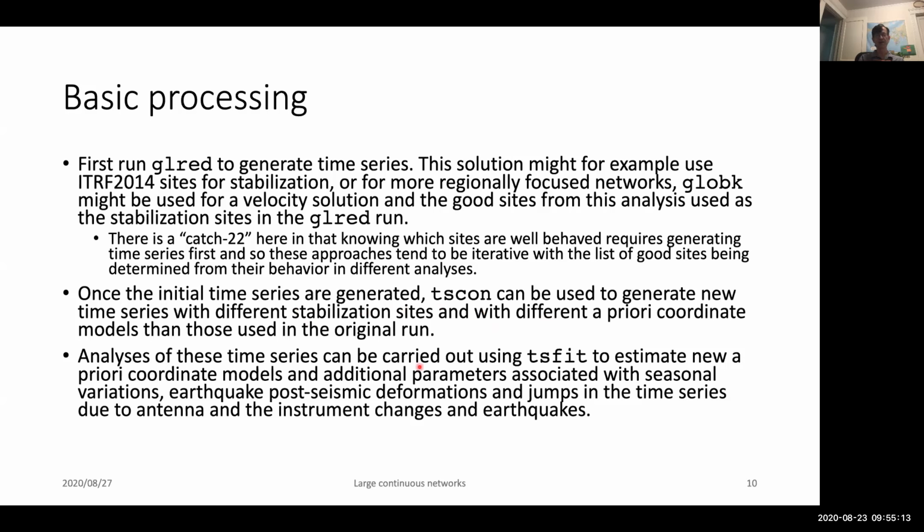You carry out the analyses of these time series with tsfit, and then there's also a shell script, sh_plotpos, that allows you to plot the time series and the residuals from tsfit, etc. And you can also generate a new a priori coordinate model, and any additional parameters such as seasonal terms that you want, earthquake post-seismic deformations, jumps in time series, etc., can all be put into this file.